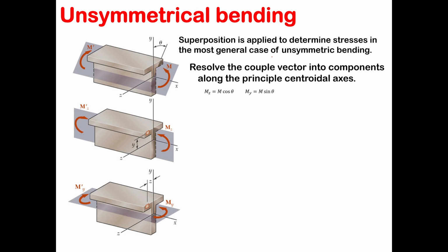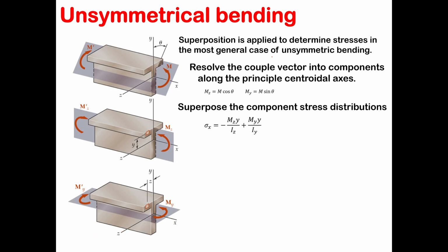You do the calculations for each one separately, and eventually you find the bending stress using an unsymmetrical moment. Okay, but then the point was, we don't know where the neutral axis is anymore. It is not going to be in the same plane as the moment anymore, right?